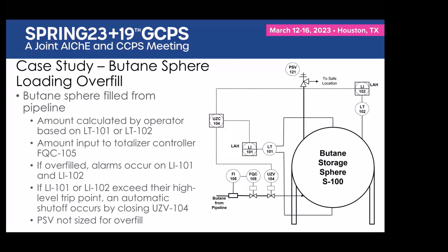So our FCC unit is creating a lot of olefins. We're buying butane. We're sending our olefins and our butane into the alky unit, and we're making highly branched paraffins, which have deliciously high octane ratings. All right, yes, I said deliciously high octane ratings. Somebody put that up on the quote board.